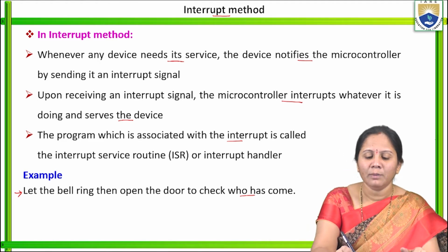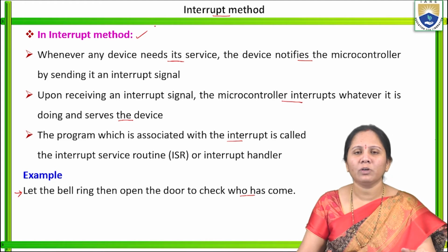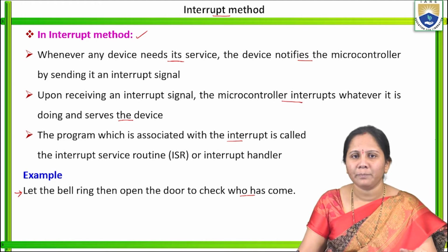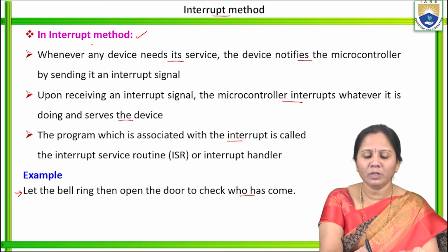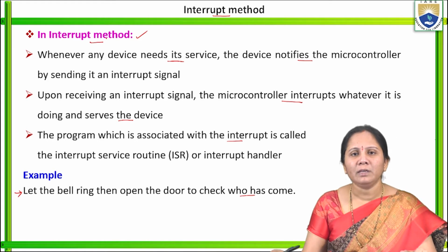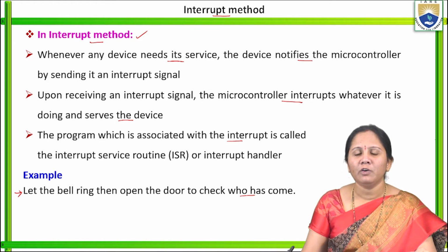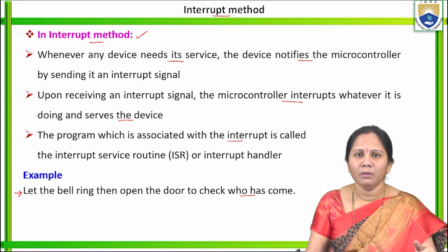So this is the main advantage. Here the microcontroller is not wasting the time. So that is why, compared to the polling method, the interrupt method is preferred for data transfer between IO devices and microcontroller.